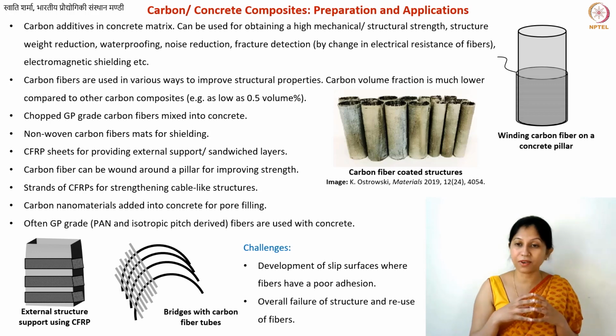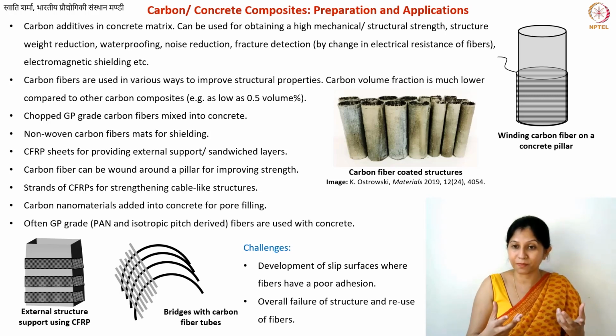So you can have a lot of breakage in the case of carbon fibers, and also the microstructure of the carbon fiber is compromised. So you may end up, for example, inducing voids that then can lead to further cracking. So the recycle of carbon fibers is also one important issue.